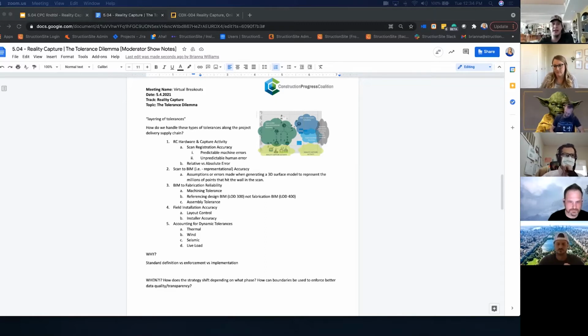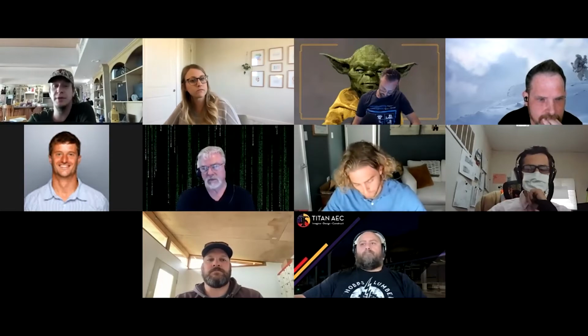The rotational accuracy of those measurements is almost identical regardless of the speed. The reason slowing it down on most scanners improves accuracy is they don't actually slow it down much. What they do is multiple sampling. With any phase-based scanner, when you go with a higher quality option or a lower quality option, they're still capturing just as many points in the hardware. They're basically averaging on the hardware rather than averaging in the software after the fact.